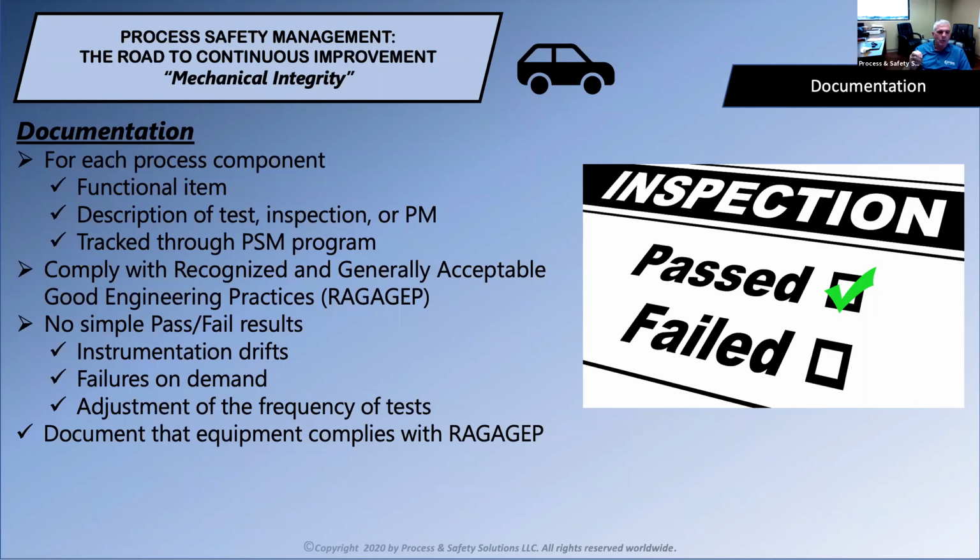We, again, are looking for failures on demand in our documentation. So if we're testing the instrument correctly, we may have situations quite often where, when they're tested correctly, they actually fail to do what they were designed to do. That would be considered a failure on demand.